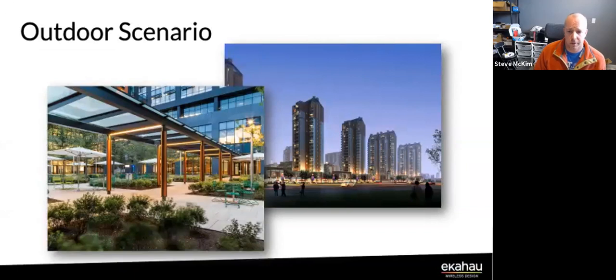But for your outdoor, in the chat, somebody made a comment that you can't always cover outdoor from indoor because of low E glass. Yeah, especially depending on your climate, your windows might be triple pane, low E, argon filled, and those seriously attenuate RF. You wouldn't think so, because you can see through it. Why doesn't the RF go through? But unfortunately that isn't the case.